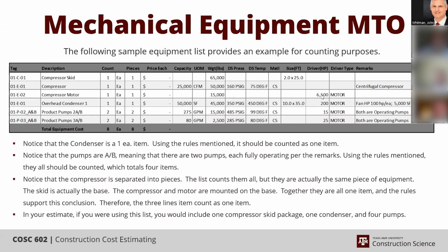To give you an example, if you have metrics that tell you that pumps are $1,200 per horsepower or something of that nature, that's probably true for centrifugal pumps, but reciprocating pumps might be $1,750, while PD pumps would be a whole lot more.